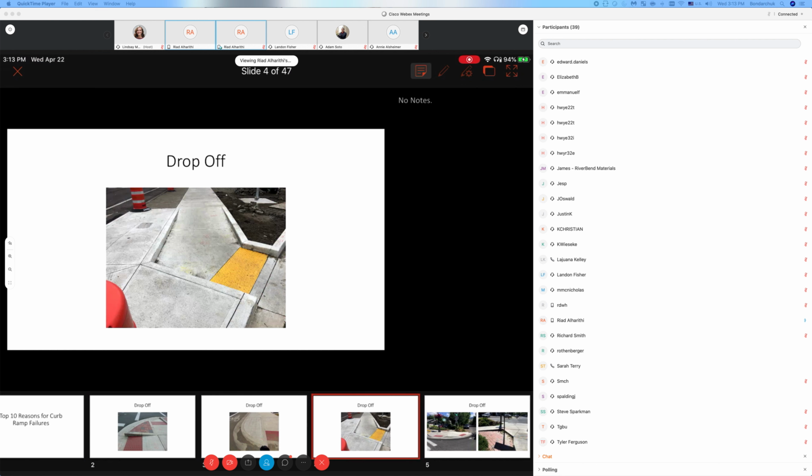Again, a similar situation. Drop-off, if a person could be wandering and dropping off. So whenever we have these return curbs, if there is any place where it's a traversable surface, it needs to be a soft surface, a landscape surface, and we saw that in the previous standard drawing that we referenced.